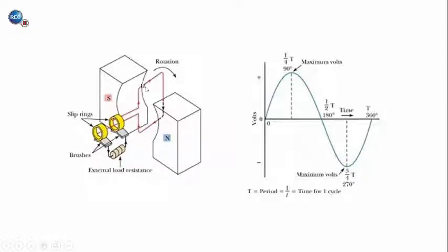And so here, when this coil rotates, this top part of the conductor sometimes passes down through the magnetic field and sometimes passes up through the magnetic field. And so down versus up is going to correspond to either the electrons are flowing in through that part of the conductor or out of the page through that part of the conductor. And what that results in is an alternating current.